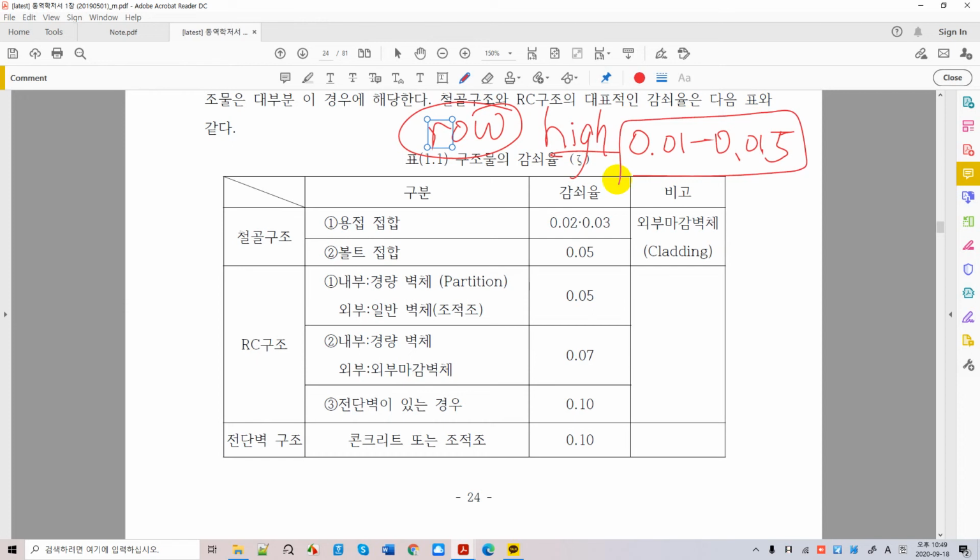Okay, so what can you say? We interpret the damping ratio for a high-rise building so that it's really difficult for us to stop high-rise building vibration once it started to vibrate, because the damping of 1% to 1.5% is very small damping to stop the building in very short time.